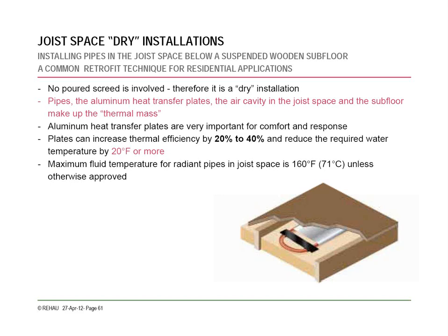Installing them without plates, though, you're really limiting the amount of output you can get out of them. Even with plates, you're probably looking at about 20 to 25, maybe, if you have a good plate system intact, BTUs per square foot.